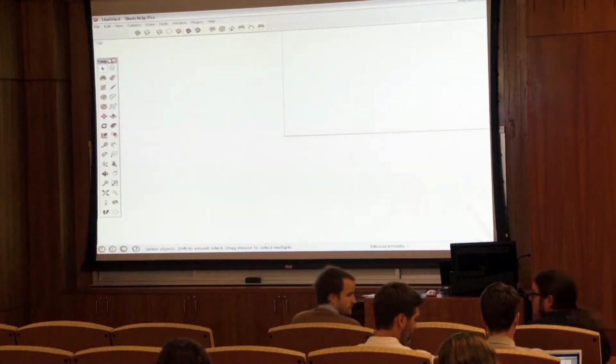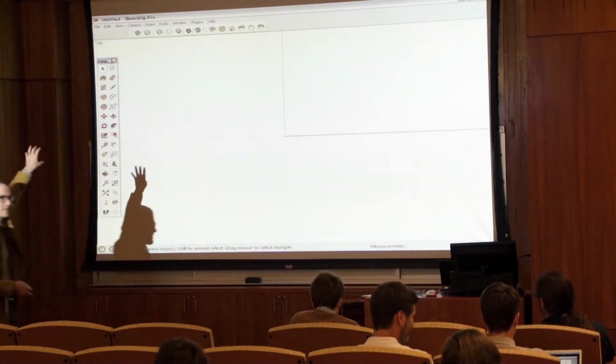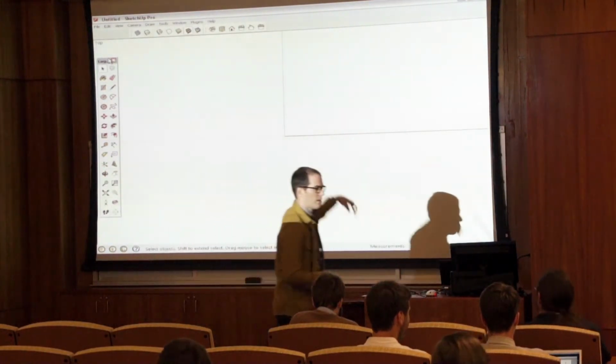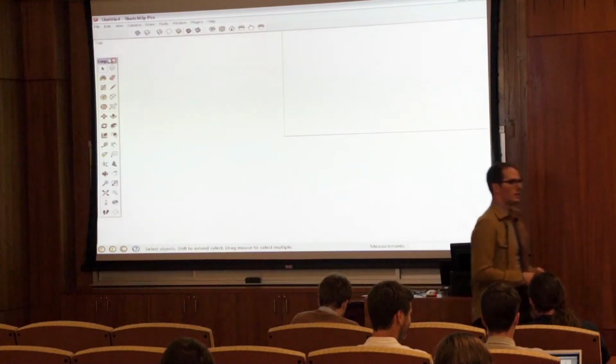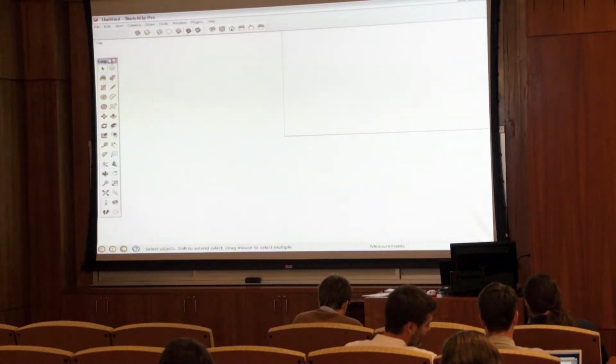So the reason why I like this is all my drawing tools are on the left. All of my display settings and elements like that are up top. You can even put undo, redo up there. You can put your shadows to turn them on and off. Other ones I usually put up there are like my section cuts. You can activate and deactivate, as well as hide section cuts. So then I try to dock up top.